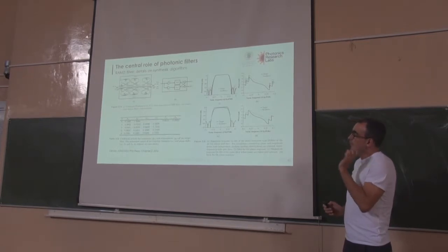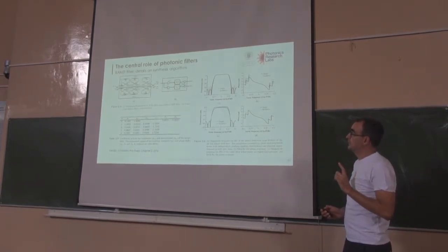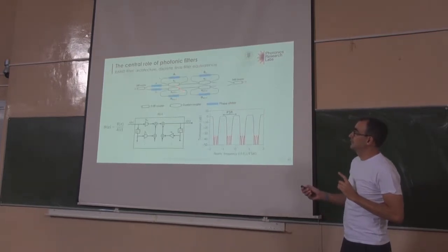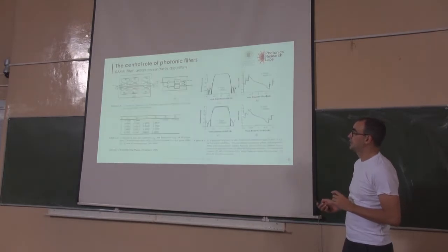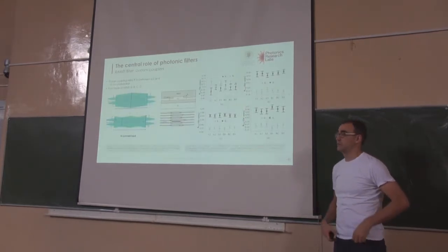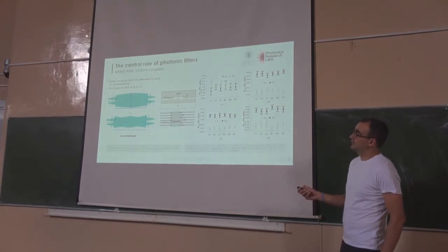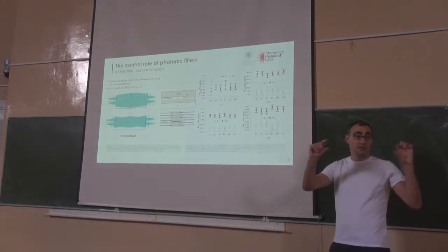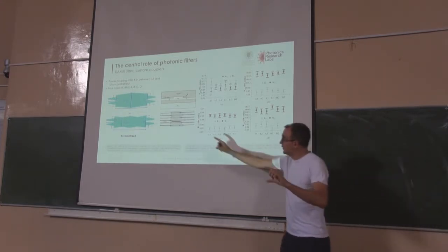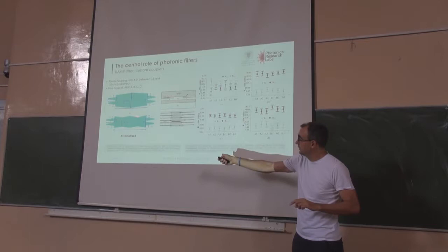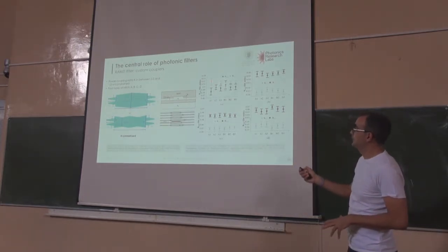Okay. Now a little bit of recall on the building blocks that are used for this filter. I said couplers and ring resonators. So basically the couplers, custom couplers, we discussed them when I was here in October. They are MMI couplers, but with a fancy shape in the middle. They are not rectangles, okay? But they have this widening in the middle, or even this stretching, widening, stretching, okay? And then those can provide any coupling constant as you wish.